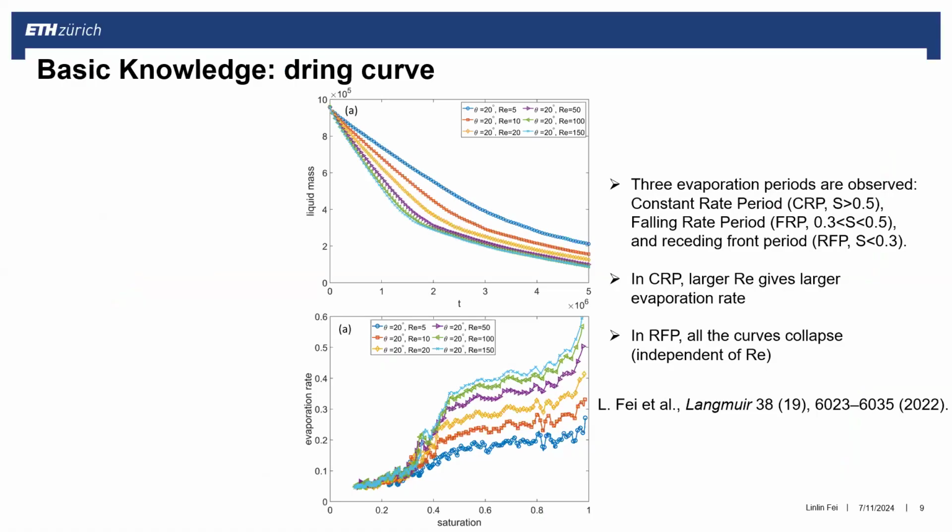Do you mean there's like a transition of the slope in this curve? Yes. No, this is because we have capillary pumping, so the liquid is supplied from the larger pores to the small pores. So the small pores in the channel level are always filled with liquid phase. That's why in the first stage, the drying is very fast. The drop of this curve is very fast.